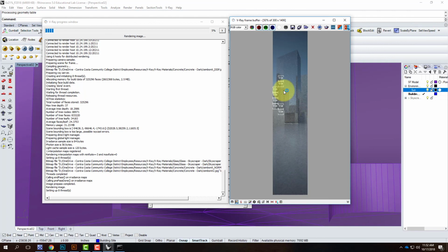So our purpose today is to actually get the sun to be set up, to get our physical camera to do the exposure, to get our block that represents our building into the city of San Francisco scene, and to be able to perform your first rendering of this scene. You'll notice that the sky in the background here goes from light to dark, and that's based on the time of day. If I change the time of day, that sky will change. If it's closer to noon, it'll be a little bit lighter. And you can do side-by-side renderings if you want to see that happen. OK, so what I want you to do at the end is to post this image as your featured image, so you get a rendering out.